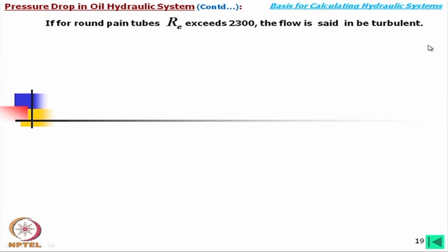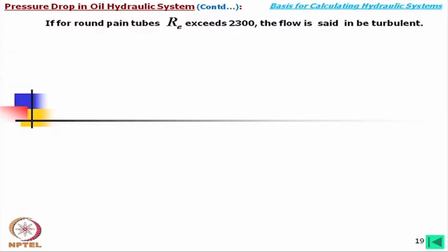Normally in fluid power, when the fluid is flowing through conduits, the flow is not turbulent, but usually through an orifice the flow is mostly turbulent, and there it is again very difficult to calculate the Reynolds number. However, by changing the orifice shape we can reduce the Reynolds number and make it laminar. But in many cases, for the best response, it is better to have turbulent flow, not laminar flow, particularly in a valve. Okay.